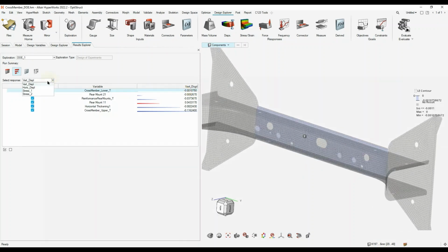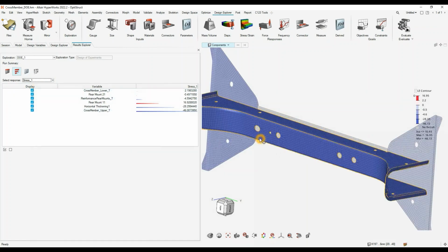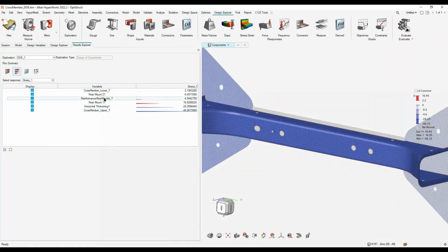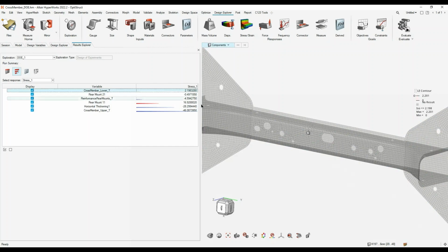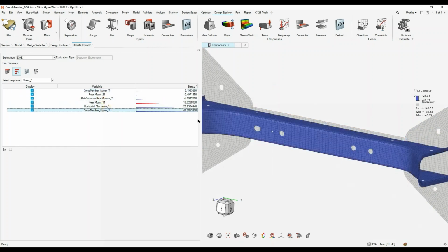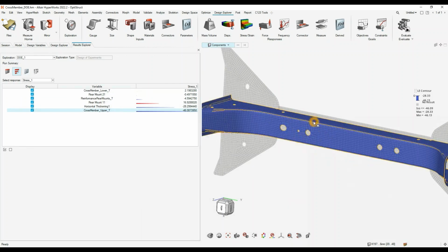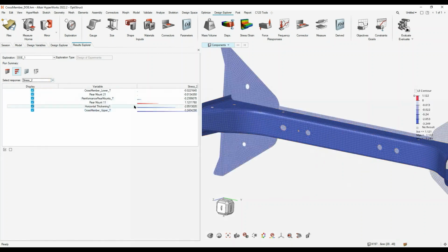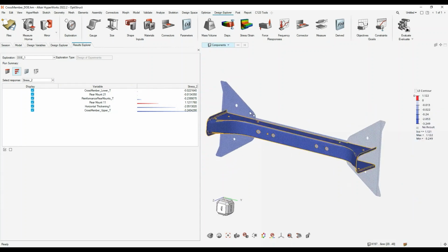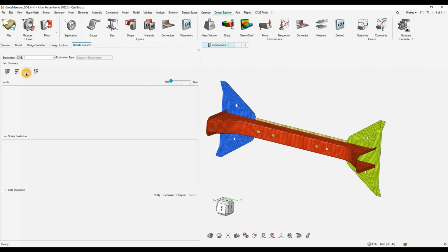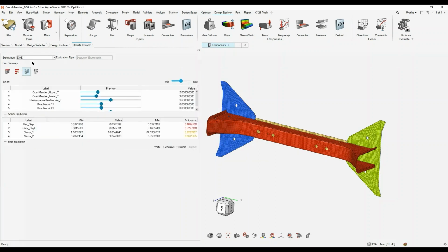And that makes sense. We can also look at stresses, and as we can see, there are some thicknesses that are positively correlated, so we need to be careful about those design changes. But there are other thicknesses whereby the thicker it is, the lower the stresses. And this does work out very nicely because the thicker this part is, the lower the stresses, which is understandable. So all of this is just a nice understanding as to which inputs really do affect those key performance indicators you care about, and where we're looking at a trade-off at the end of it.